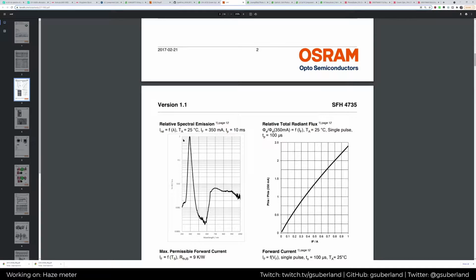But anyway, the point is that as long as the receiver is fairly selective, or the other option is to put an attenuator on. So, say for example, anything under about 750 nanometers, you start a roll off where you don't end up transmitting that light. Because really what we want to know is that there is some 1050 nanometer light going through there. Now, this is all going to be in an enclosure, so there's not going to be any random IR or UV coming into the device. You won't be able to get any light in there.